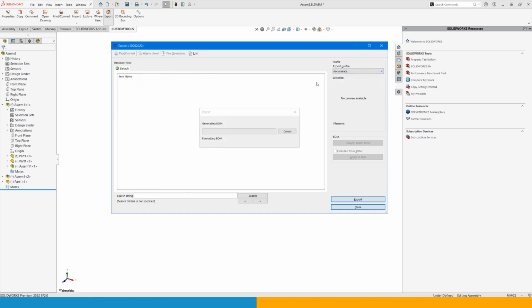If I go to the accumulate BOM, we should now be able to see that we have still 1 top level, but in this top level we have 2 assemblies, as before. To create these 2 parents, we need these 4 children.